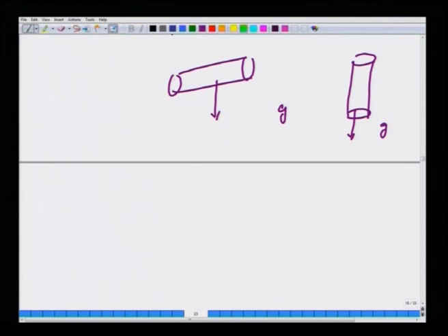Here the projected area is going to appear like a circle, pi dP squared by 4, whereas here the projected area is, sorry, there is no pi here, just dP times L, because it is going to appear like a rectangle of dimensions dP times L. So, the drag coefficient is defined differently because the projected area is very different.